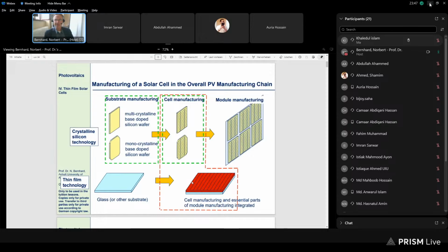Okay, let's come to the 2-6 cells, the cadmium telluride cells, which are at the moment the most important. As I said already, cadmium telluride, with respect to the production volume, and copper indium gallium diselenide, you can also consider as a 2-6 semiconductor. That means the Roman numbers always refer to the group in the periodic table of elements, because you see the tellurium and the selenium are from group 6, of course.